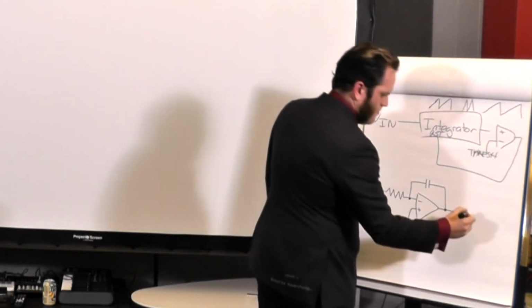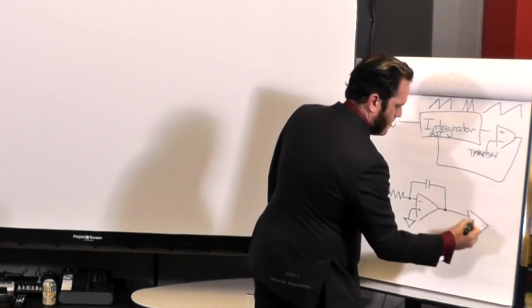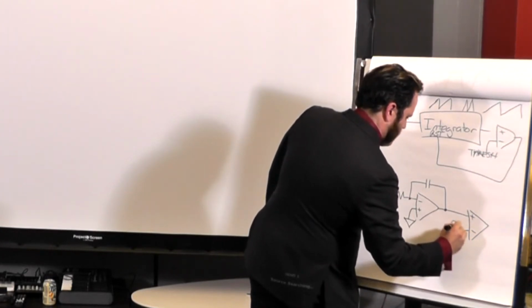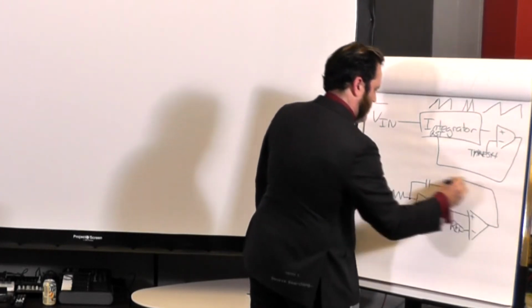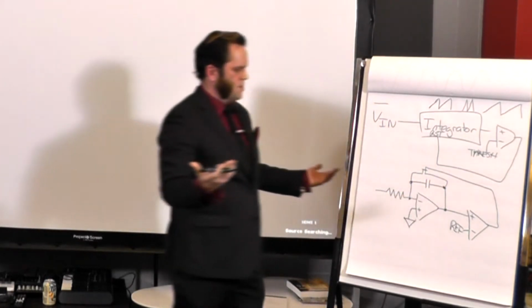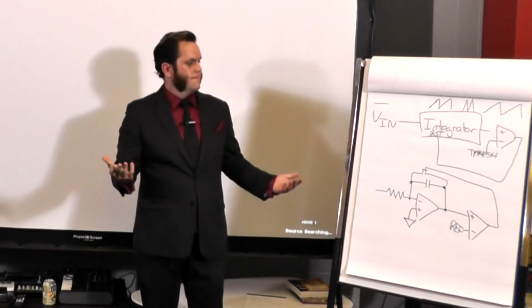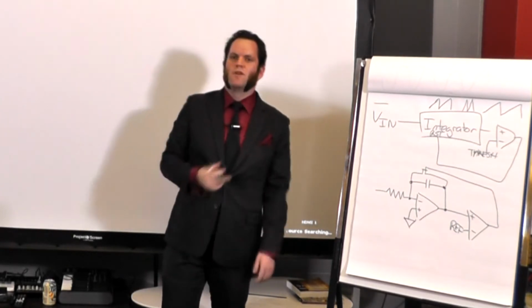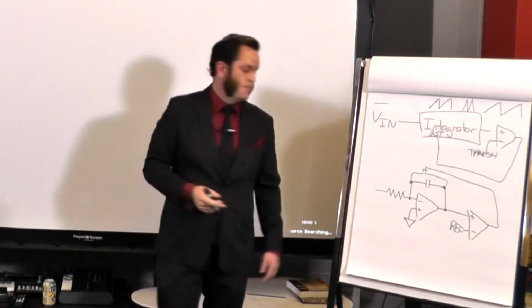But here's the cool thing. We take that comparator over here, tie it to a reference, have that hit a thing like a JFET right there that shorts out that capacitor and essentially resets it. What was that, 5 parts? A 5-part voltage-controlled oscillator. Pretty cool, huh?